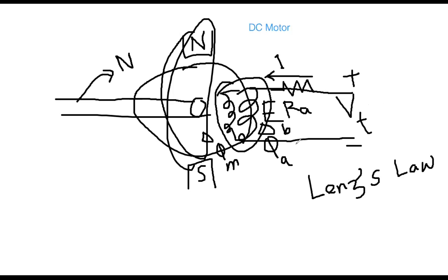So if I write down the armature current equation, how much current was entering the coils? The terminal voltage I applied is the initial applied voltage to the motor, and later the back voltage EB is built up, and then we divide by the resistance RA. And you see, this makes sense.